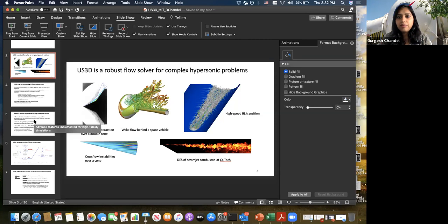And we actually did not even find that out for the first few months. We got a solution and it was giving us some stable results, giving some reasonable shock speed. We did not know what the actual shock speed should be, but it was kind of a rabbit hole to chase. When we tried to validate that against analytical shock tube simulations for lower Mach, we saw that it predicts a wrong shock speed if you use just 4 sub-iterations.